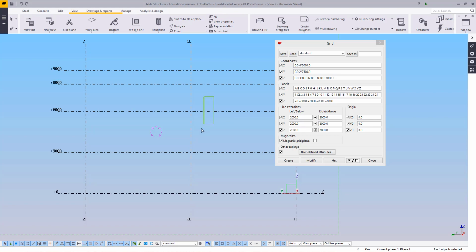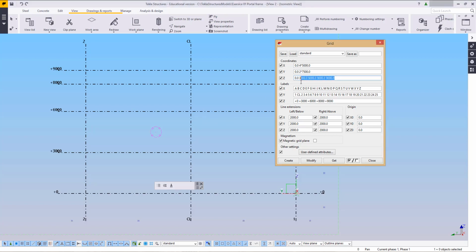and what we are going to be doing is simply take this and I'm going to say I want my columns to be about 5 meters high and the apex of my roof is going to be 5.7. Now, unlike your normal X and Y axes, Z-axis always work from the bottom or from the 0 plane. So this is going to be plus 0, plus 5 meters, and plus 7,500, 5,700.